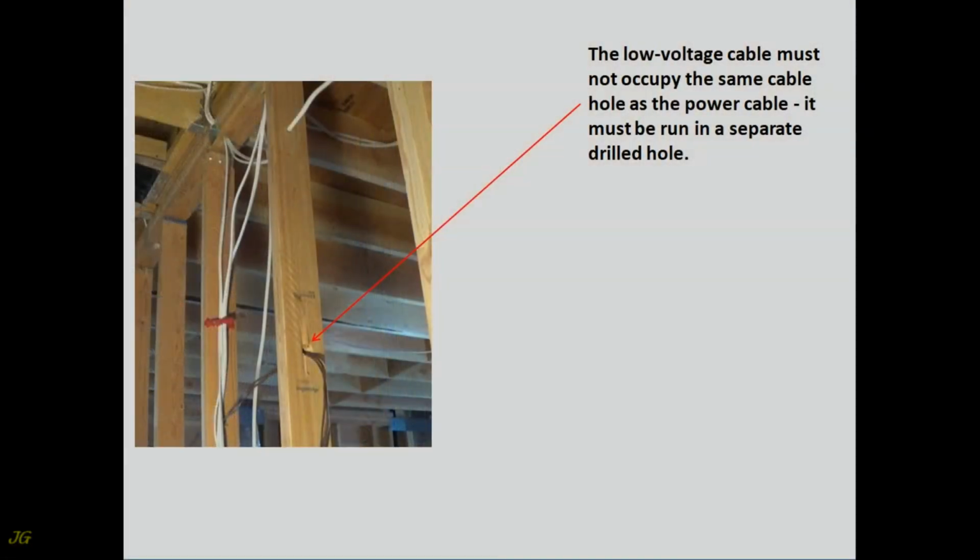The low-voltage cable must not occupy the same cable hole as the power cable, it must be run in a separate drilled hole.